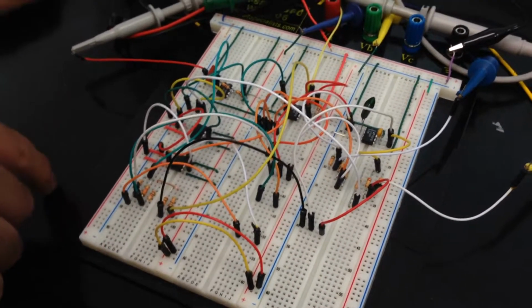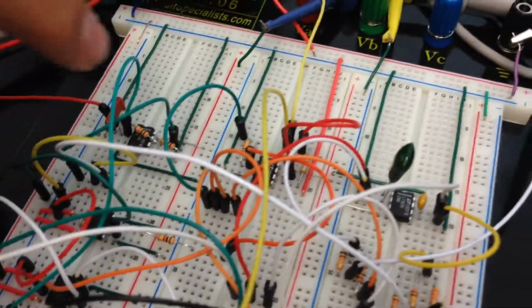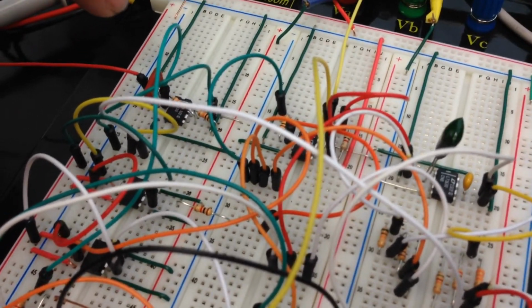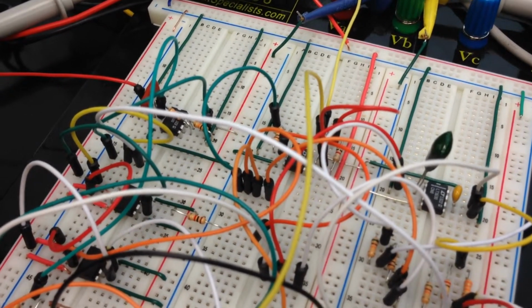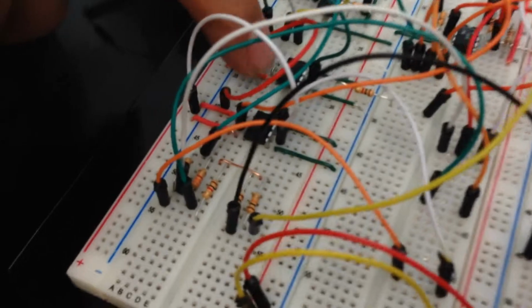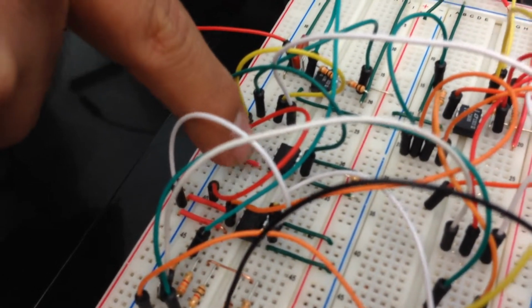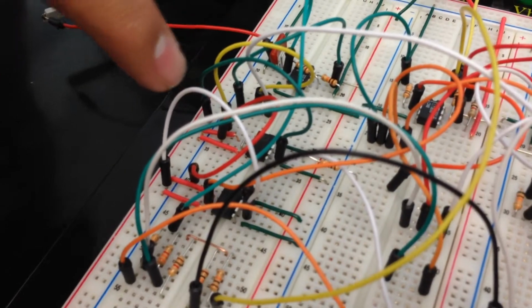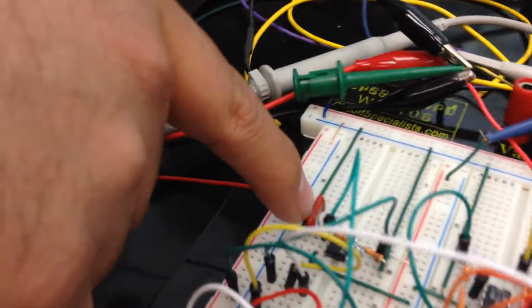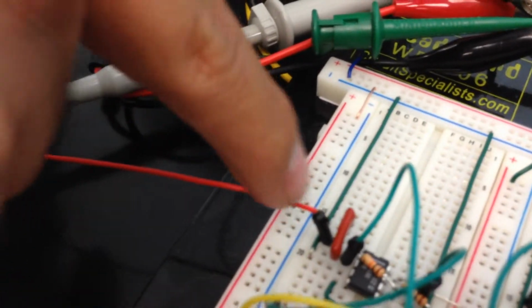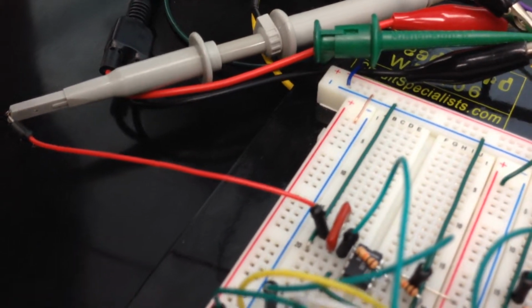What we have here are 3 LT1630 op amp chips. Each one of them has 2 op amps in them, giving us the right amount that we needed to simulate our circuit. Then we have our AD633 multipliers on this side, which we passed our x signal through to get x squared and x cubed. The multipliers actually have a scaling factor of 1/10, and that was compensated with the resistor values. The op amp here has a capacitor over it, and this is what is actually going to be doing the integrating for us.